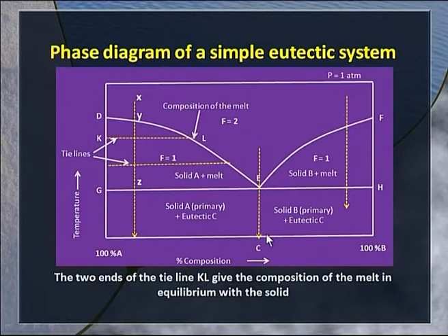It will be very interesting to study the behavior of a system in which the composition corresponds to point C here. C is the eutectic composition. If you heat it and take it to the molten state and then cool it, as you reach point E, the system becomes a 3-phase system, because the two lines intersect. Solid A and solid B crystallize out. 3-phase system means number of degrees of freedom 0, the system becomes invariant, and cooling is resisted till one of the phases disappears. In this case, the molten phase disappears and then you go below the solid S curve.